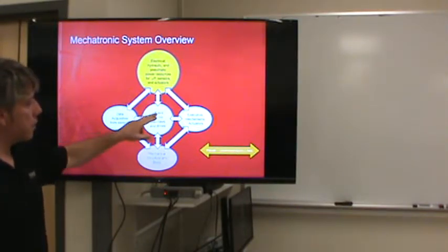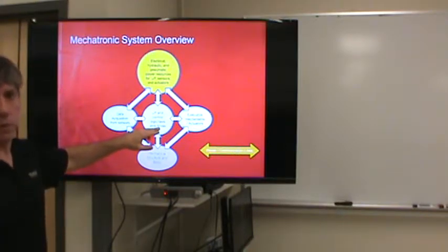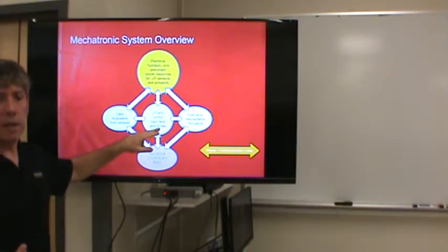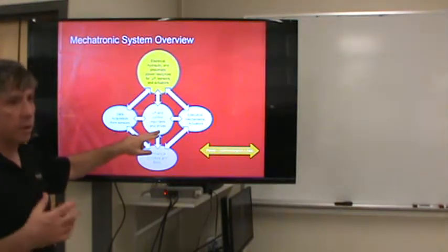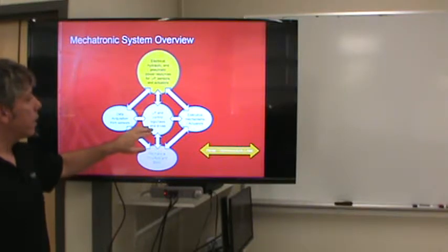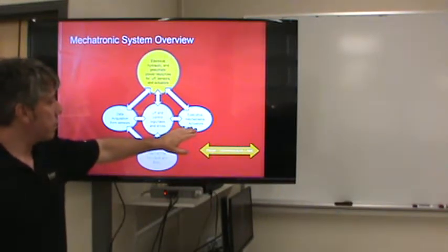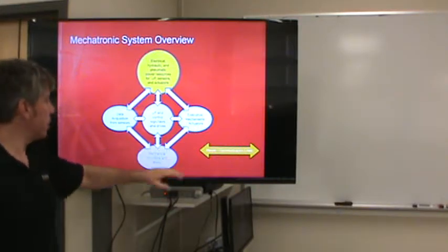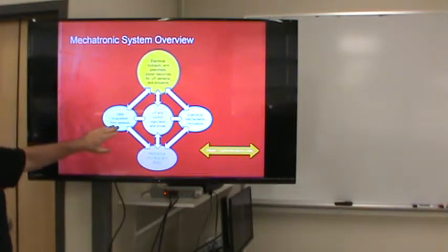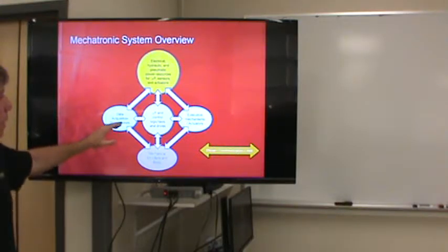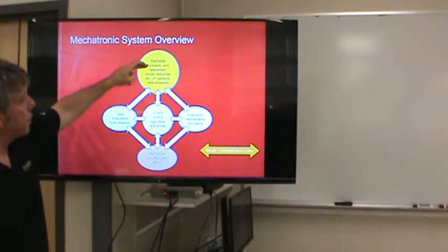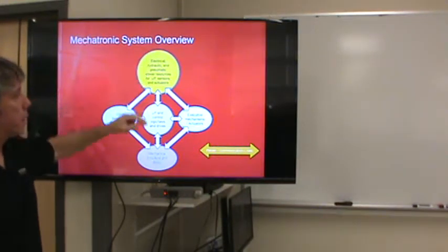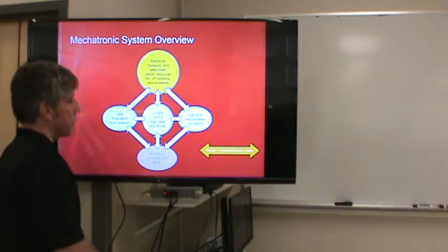So this is not only the microprocessor, it's also usually the electronics for a drive. A simple drive system would be a relay. And the mechanical relays are a little bit antiquated and imprecise. So today we're using a lot more electronic relays and amplifiers and things that are semiconductors. Then there's the executive mechanisms and the actuators, the things that are actually going to do the motion. There's sensors that acquire data and communicate with the microprocessor and the drives. And then finally there's the electrical, basically the power sources here, that drive all this and make it work.